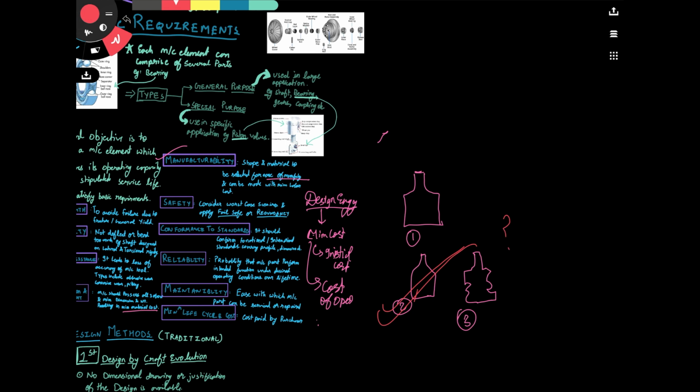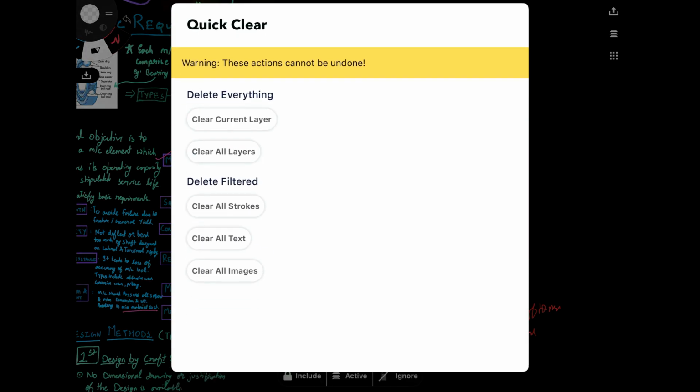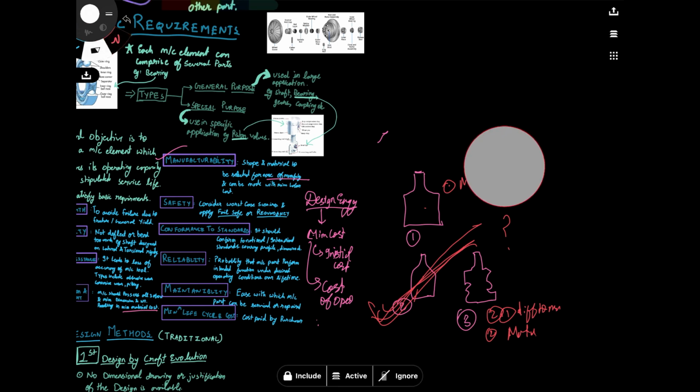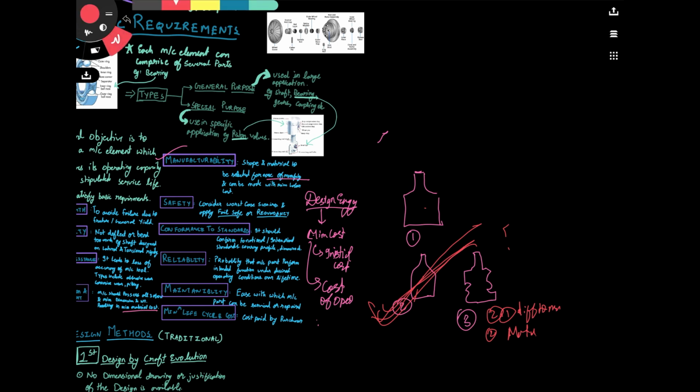The third one lacks two things. First, it's difficult to manufacture. Also, the second thing is that material cost will be more in this, right? The first one can be easy to manufacture, but the material involved is more, right? With the constraint that all three contain the same volume, in that case I will prefer the second one, right? Okay. Now coming back to the topic. So we discussed manufacturability also.